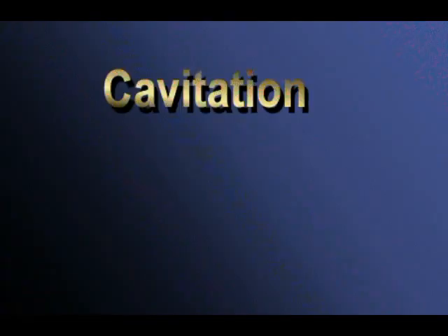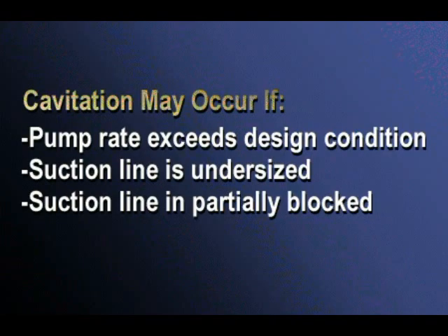The next term to introduce is cavitation. Cavitation is the term used to describe the action of an operating centrifugal pump when it is attempting to discharge more water than suction can provide. This can occur when a centrifugal pump is operating at a capacity higher than its design condition, the suction line is undersized, or the suction line is partially blocked with debris, or a partially closed valve.